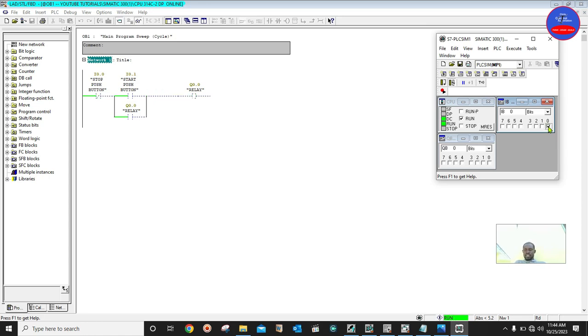You see that now my hand is still on the push button. So now this contact is still open, right? The current is only at this side. All right, so it can flow through this side. Okay, now the relay is de-energized. So let's see the output. You see, automatically it has been unchecked.